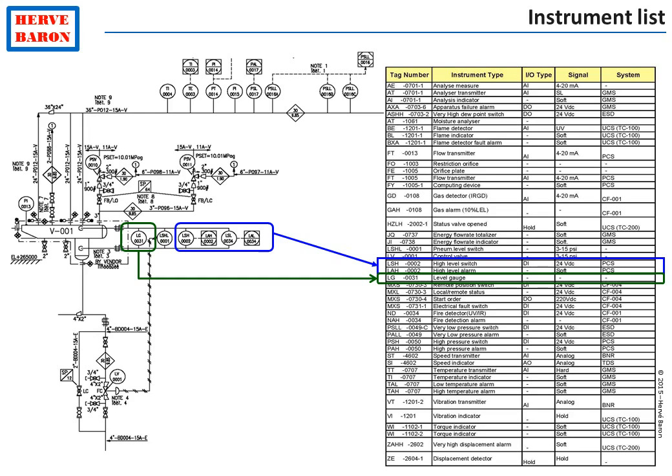Once the instrument list has been produced, each field instrument must be specified. A datasheet is produced to this end. As we have seen, a process datasheet has already been issued for some instruments such as control valves, pressure safety relief valves, flow instrument. For the other instruments, the process information is available on the heat and mass balance.